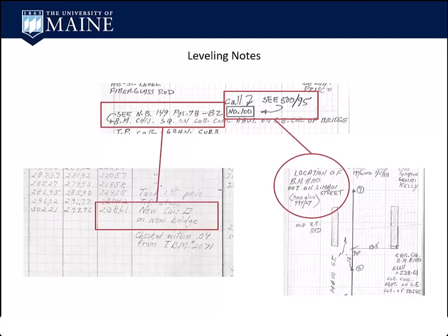And then the other node is book 500, page 95. So here on this page, he's giving you a location of it. It's an old railroad bed on South Main Street. It's Cohasset. Now we could see that in the other page. And then there's the location of the chisel square. He's described it. Corner concrete abutment on southeast corner of bridge. So if you need to go out and look for this, there's a description on its location and you can find it. Never have enough information.